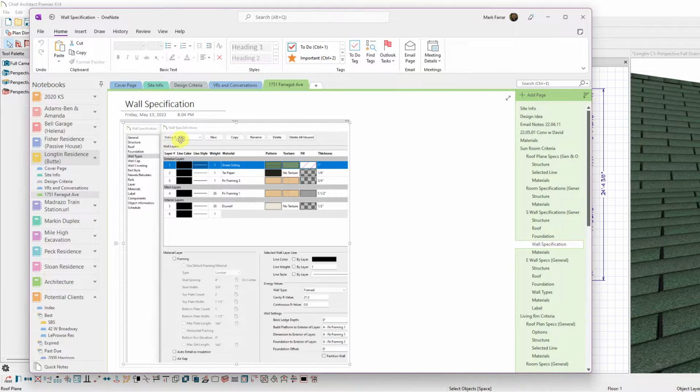So this is how I built the wall, and in this case, it's an older home, so I actually call this siding 1900s because tar paper, and then inside of that there's a fir framing, which is going to be typically 1x6 to 1x12. And it can even vary in one wall. So don't know really what I come across, but it's all usually about 3/4 thick. Then I've got studs, which actually are 5.5 for the most part. I have run into some 5 3/4 and even some true 6s. So it depends on the mill, and I guess who was in charge that day.